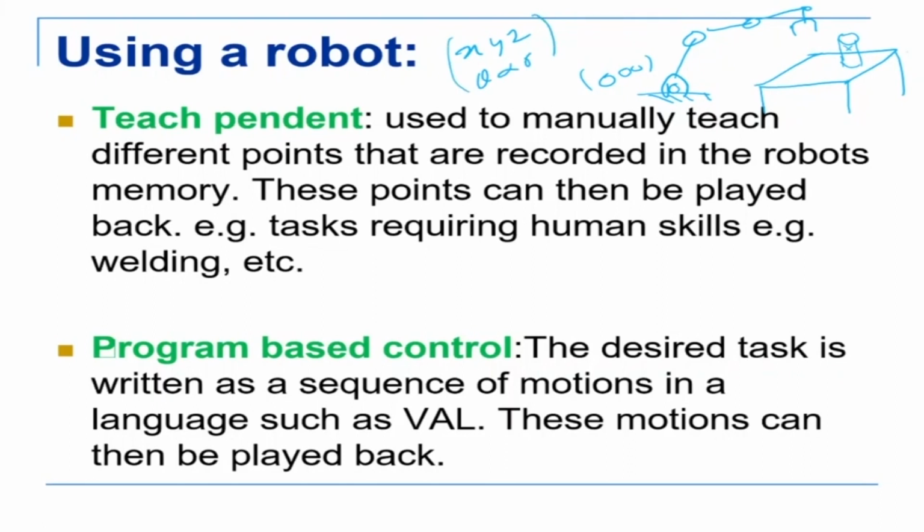Now no sensor will actually give you the 6 parameters of an object in space. So if I say with respect to this base 0, 0, 0, what is the x, y, z, theta, alpha, gamma of the object here? How would you find it? There is no way. At most you can get the distance by using a laser like this, but that doesn't give you the orientation. So we can use things like computer vision, but then again there are other issues. So please note this point, that when we have to find the coordinate of a point in space, position and orientation, it's not very easy.